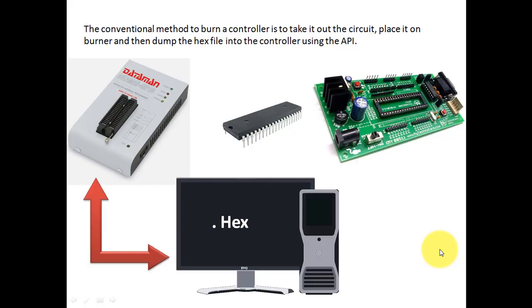In the conventional method of burning the microcontroller, we have to take the microcontroller out of the application board and put it into the universal programmer. Then, using the burner software, we have to send the content of the hex file from the PC to the burner. Then the burner dumps the code into the microcontroller flash memory.